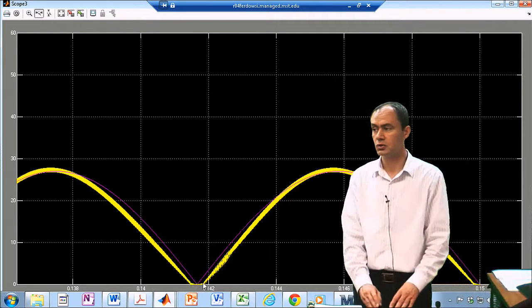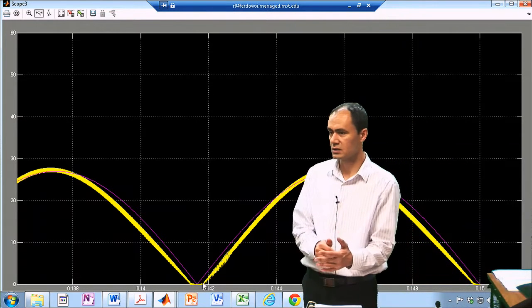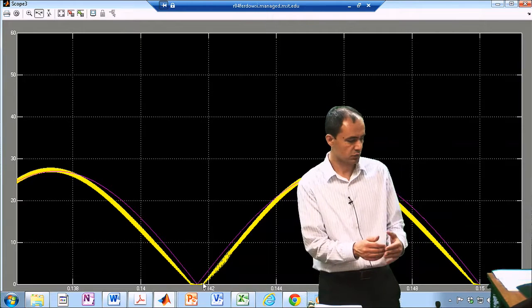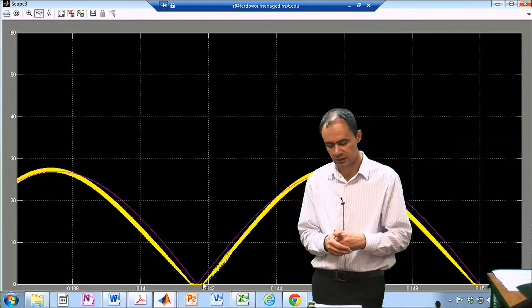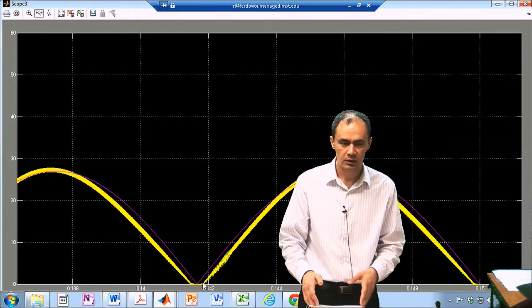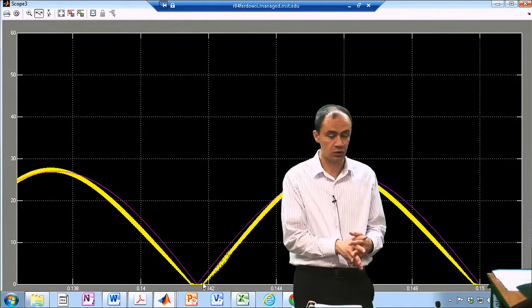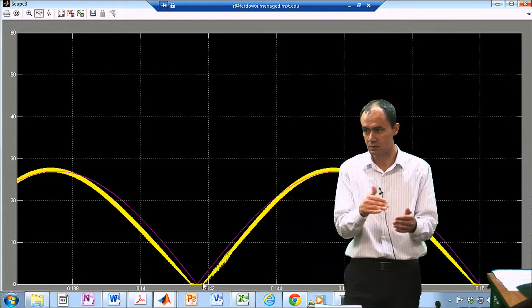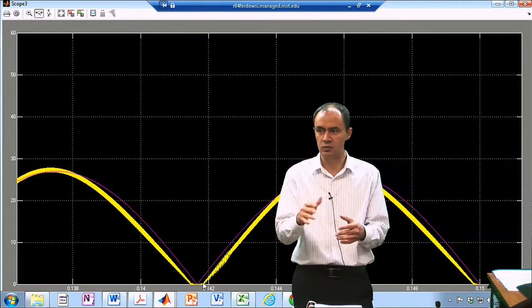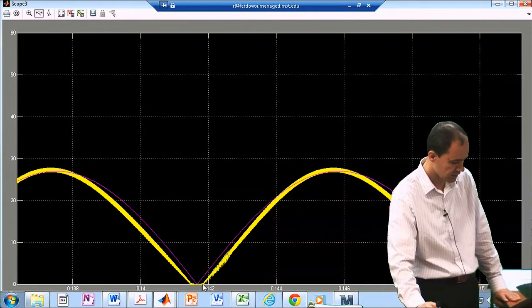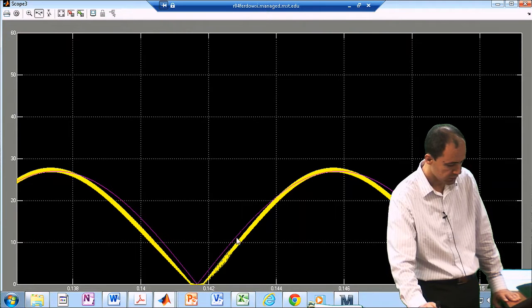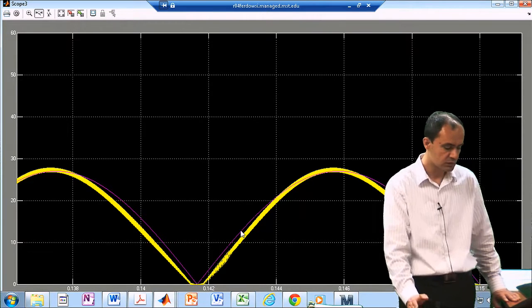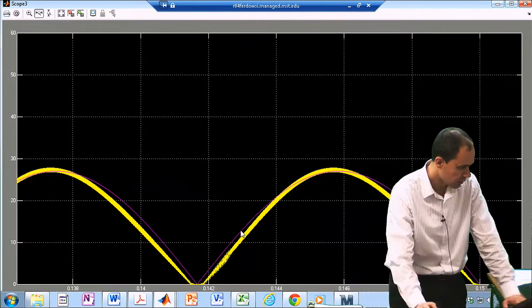And that is because you're doing peak current mode control, and this is because of the external ramp, okay? So your reference is so small, when you subtract the external ramp from it, it is actually forcing your inductor current to follow a negative number, and because this is a boost and it cannot follow anything negative, it just remains at zero. So we can see that for a little while, you're actually hung up on 0. There is a little bit of an error over here, and we will talk about why these errors occur.